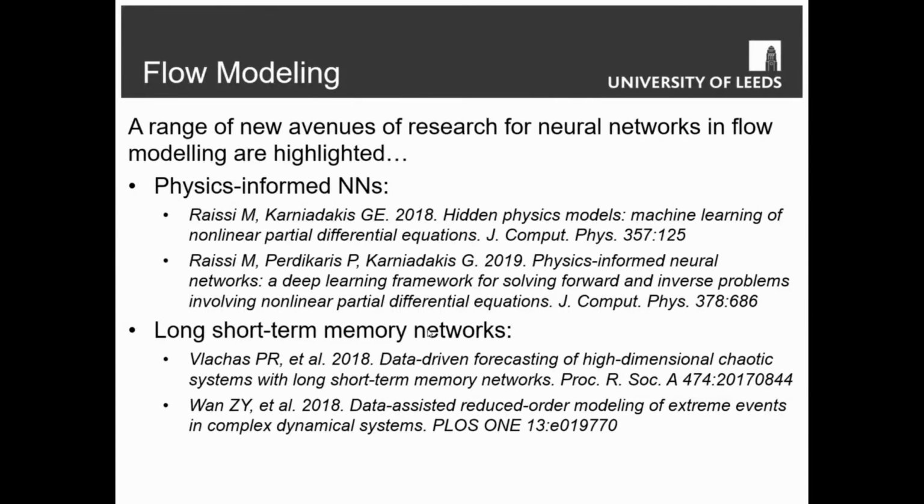What that misses though is that you only have a snapshot at one time to produce forward. If you were to use the flow field at earlier times, for example time tn minus 1, then you could look at the difference between the flow at tn minus 1 and tn to see how it's changing. So as well as using what the flow is at tn, we can also use how it's changing in order to get a better approximation of the future.